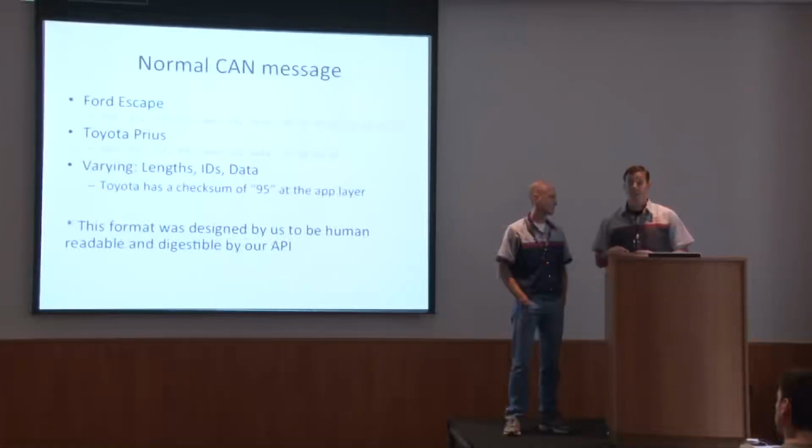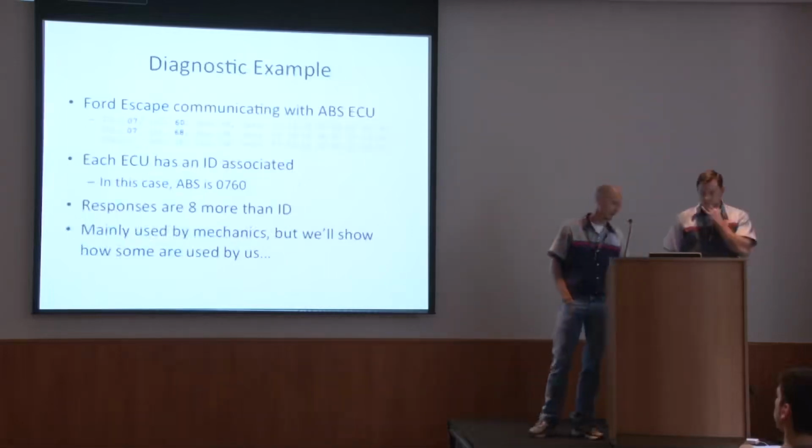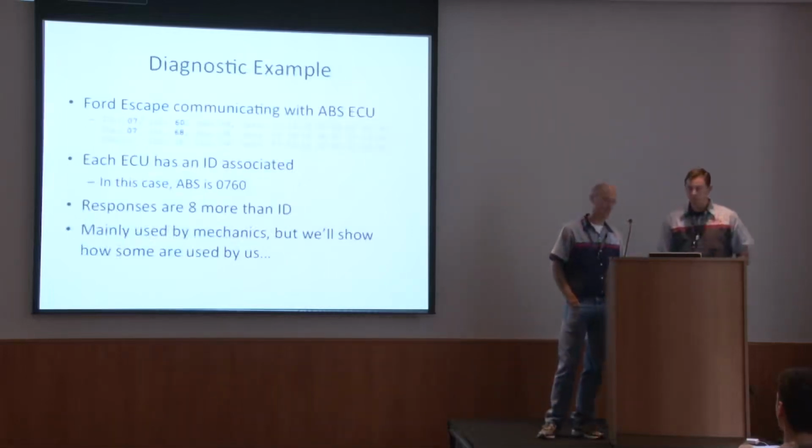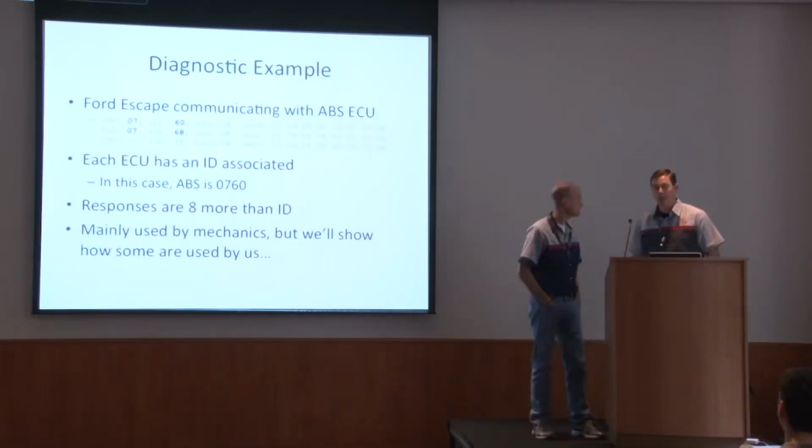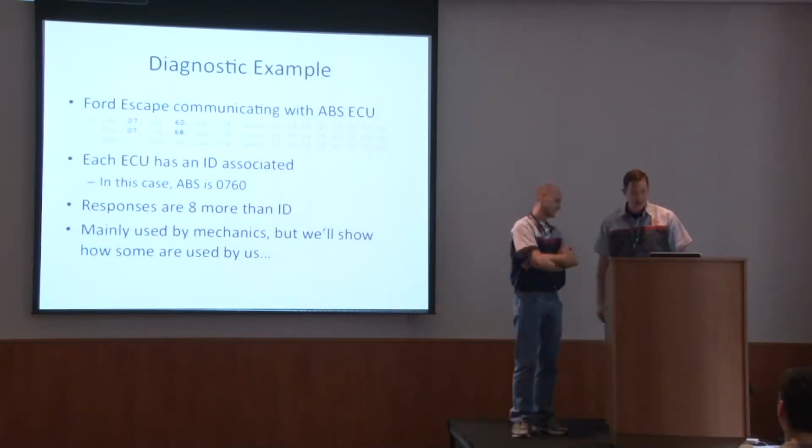So these messages are constantly being put out onto the network. They don't occur when something happens. The data bytes will change when certain events happen, but generally speaking, you'll see the message being spit out at a constant rate. And the 8 bytes is the most that a message can have. Yeah, the 8 bytes is the biggest.